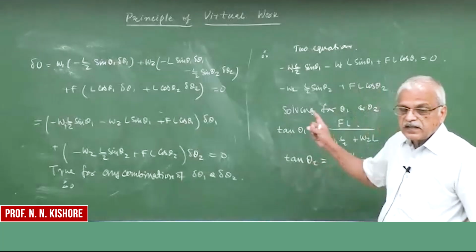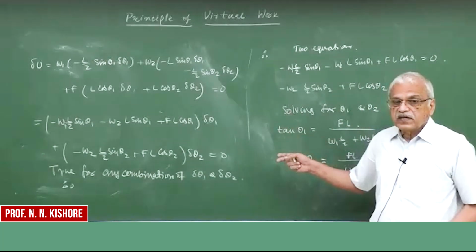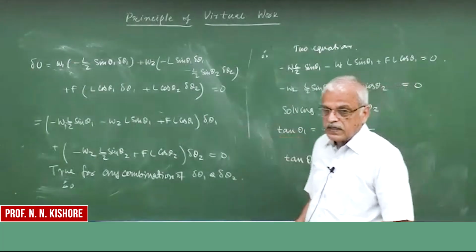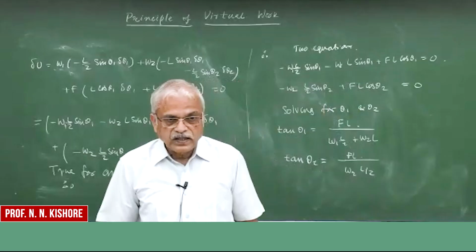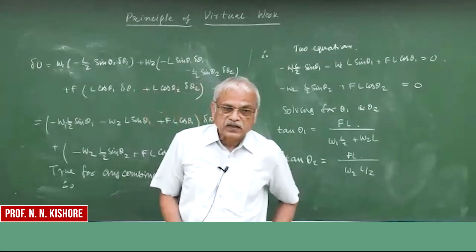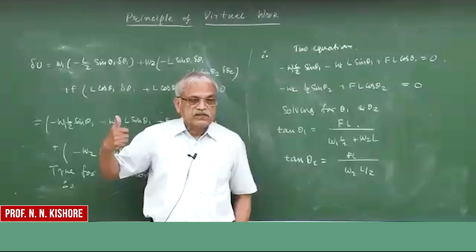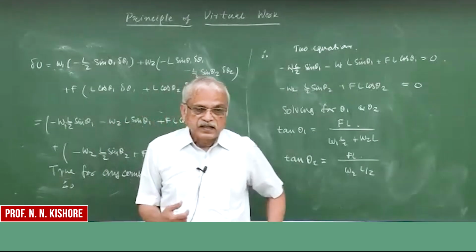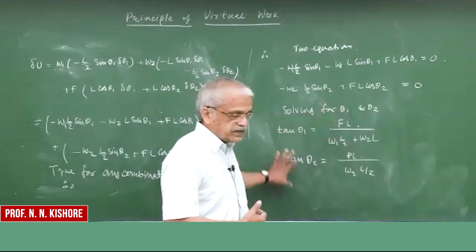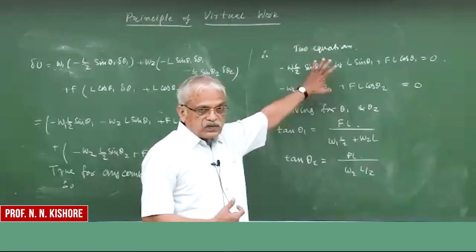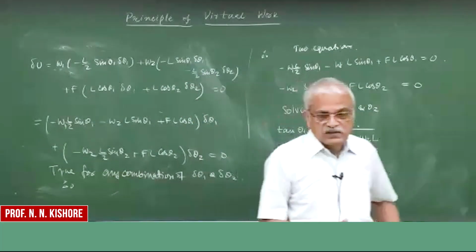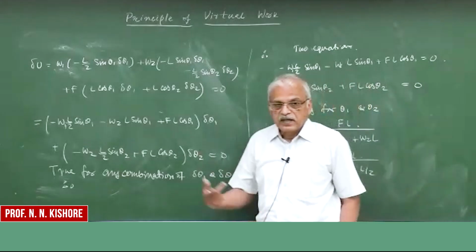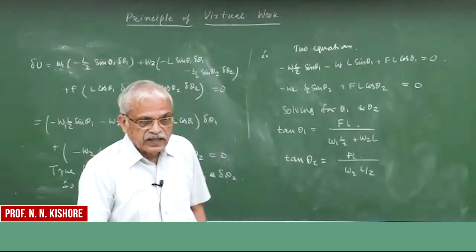The only thing is that this will not give an equation for non-active forces. It will give you the equations for only those force components which will do the work. If you are interested in finding out the reactions, then you get these expressions and go back to the application of free body diagrams. Draw a separate free body diagram and then solve for the unknown reactions.